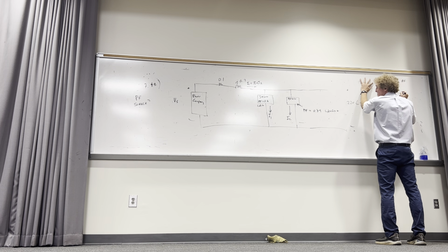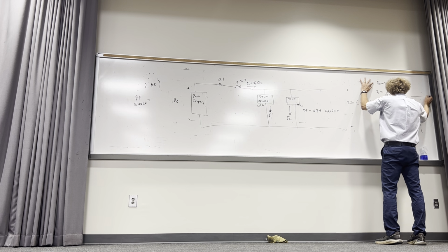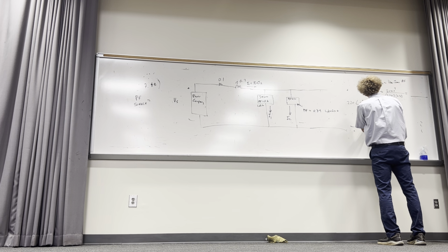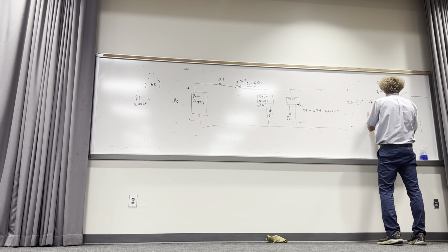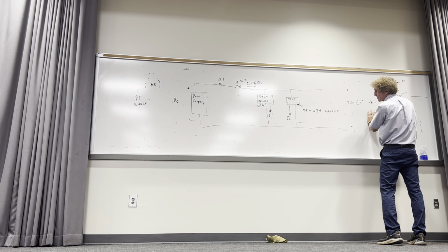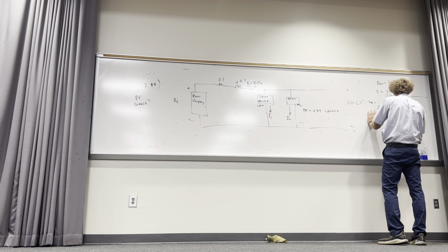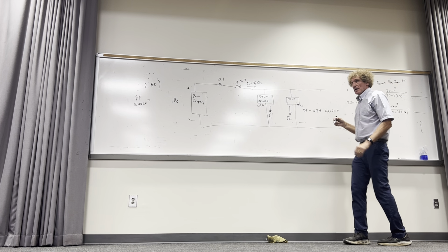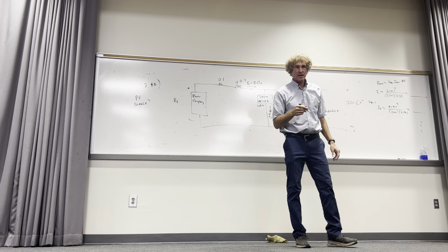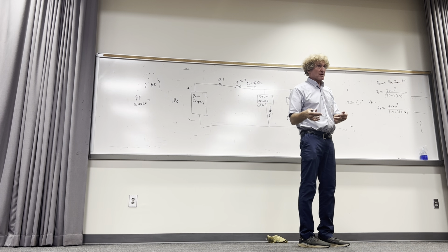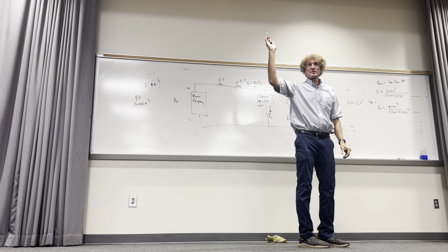And the power factor on that one is 0.8. And likewise, I can also get I2 in the same way by saying it's 40 kW divided by 220. And there the power factor is 0.74. So this is just magnitude, we'll get the angle in a second. Is everybody following me why I'm doing what I'm doing?